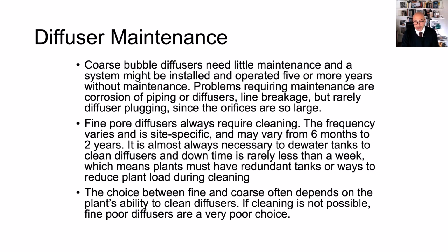Coarse bubble diffusers require little or no maintenance, and that's one of the benefits. They also have very little pressure drop. Fine pore diffusers are required to be cleaned. If you can't clean them, you should never specify them. They need to be cleaned on average once every 2 years. That's a very gross simplification, but based on observation of hundreds of tanks, we can say with confidence that once every 2 years is necessary. Some tanks with long SRT foul a little less, so maybe you could extend it a little bit more, but not by much. And after that, you will reach a plateau, the lowest possible efficiency you can have.